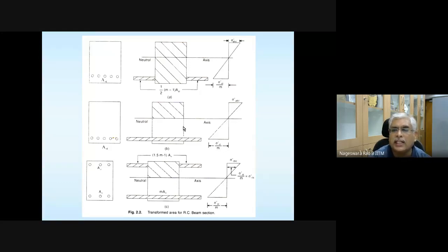Please note that steel is good both in compression as well as in tension. So we can even provide steel. Please note that if you take a rectangular section subjected to sagging moment or hogging moment, the extreme fibers are going to be subjected to the maximum stresses.